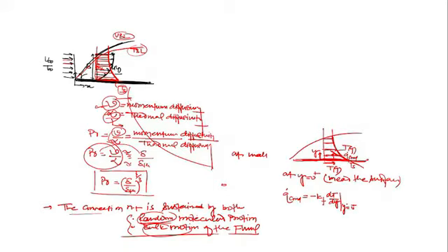It's a heat flux by Fourier's law, and at the same rate, the heat conducted from the surface of the solid into the rest of the fluid is going to be transferred via a combined mechanism. Which combined mechanism? Random motion as well as bulk motion, and that is combinedly called convection heat transfer.